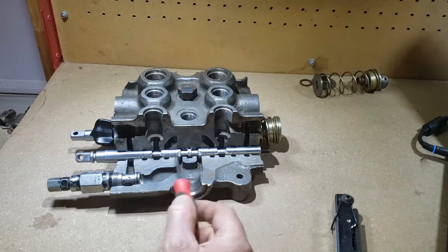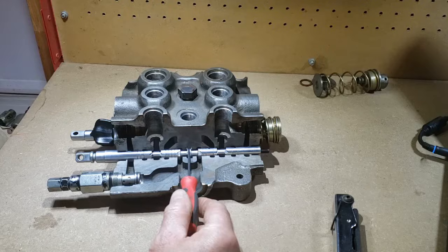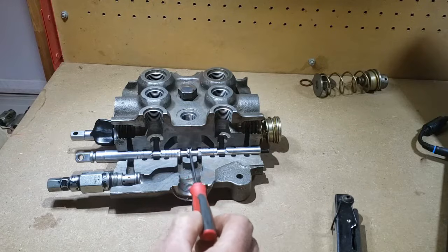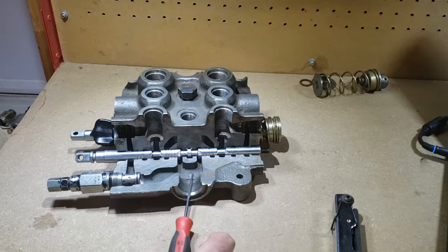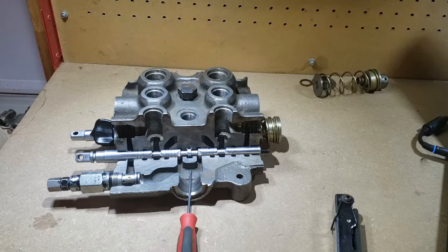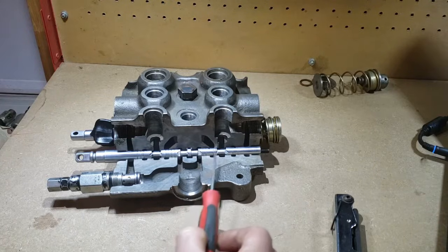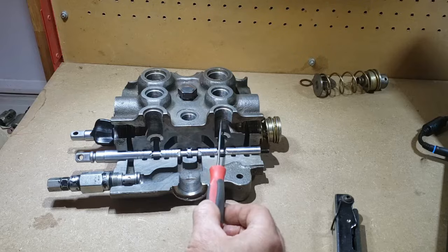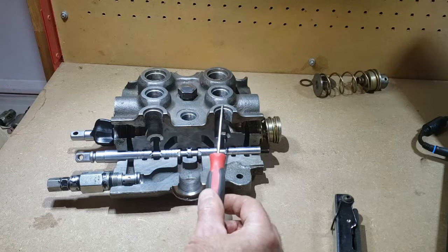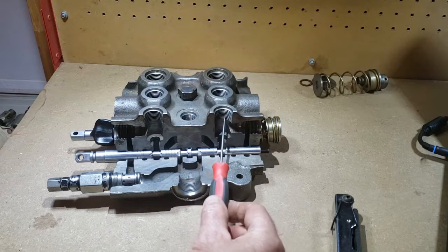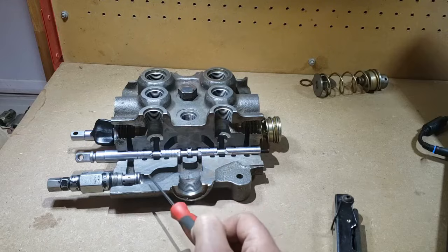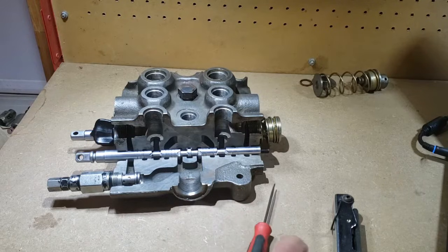Because we've put the control valve back into hold and the open center flow path is opened up again, the pressure at the pump supply is going to drop back to not quite zero, but again, we've got cooler and filter back pressure, so maybe 100 psi. So we've got 100 psi pump supply pressure, and let's say for discussion purposes, we've got 1,000 psi waiting in this work port because we're supporting a load off the ground and trapping that oil.